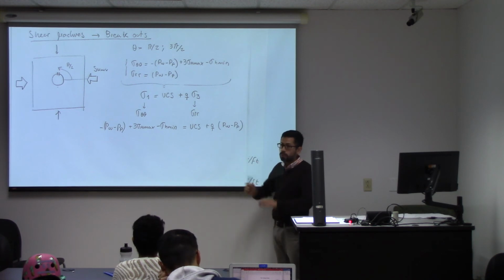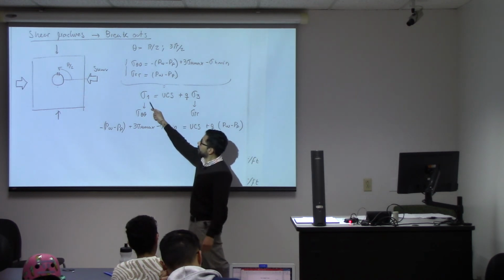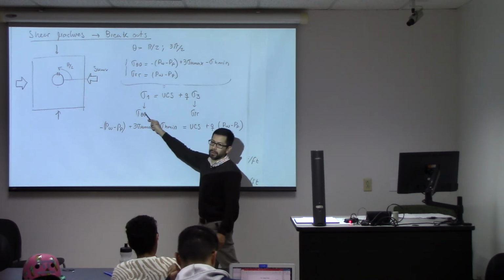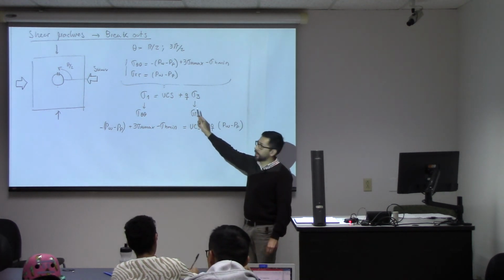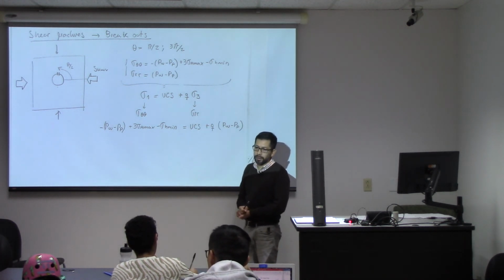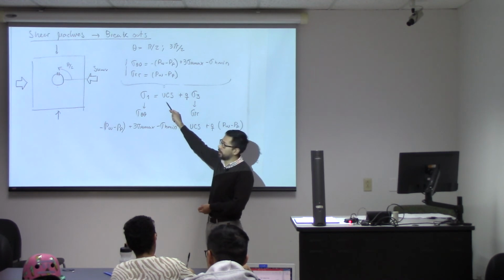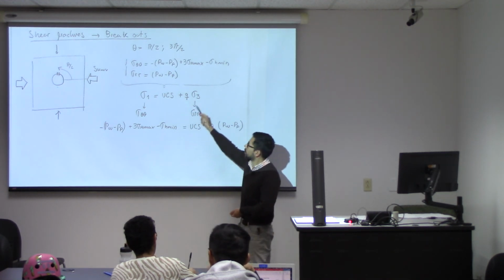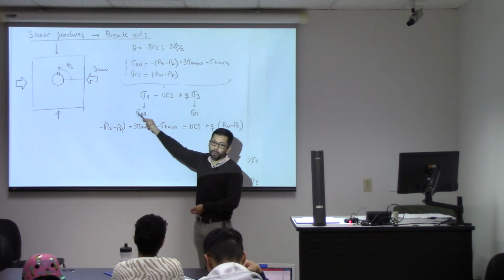So the more wellbore support you have on the wall of the wellbore, the further you can go in magnitude in sigma theta theta. For example, in the case of uncemented sands without any cohesion, without any unconfined compression strength, if you don't have any support, you cannot drill a wellbore.